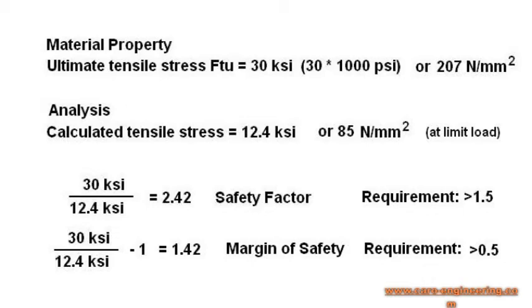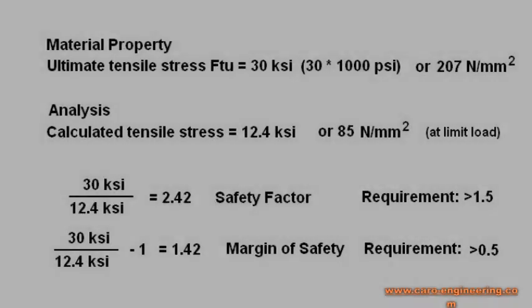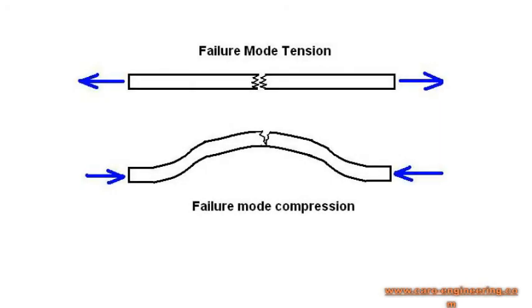As we said in the loads analysis, you normally only need a safety factor of 1.5, so this part would be okay to use as is. Some people use a slightly different definition, the margin of safety. Every material has different properties, so you have to look up the correct design allowables for what you are using, or come up with them yourself by testing samples to destruction. If this was all there was to it, structural analysis would be pretty simple. Unfortunately, it isn't. I will give you some more examples.